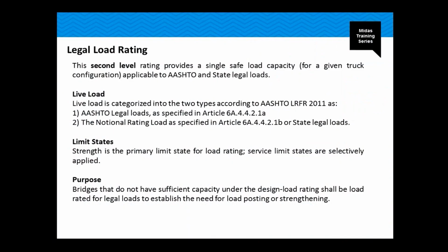Then we have the legal load rating. This is the second level rating, which provides a single safe load capacity for a given truck configuration applicable to AASHTO and the state legal loads. In this case, the live load is categorized into two types according to the AASHTO LRFR. One, AASHTO legal loads as specified in Article 6A.4.4.2.1a, and the notional rating load as specified in Article 6A.4.4.2.1b, or state legal loads.